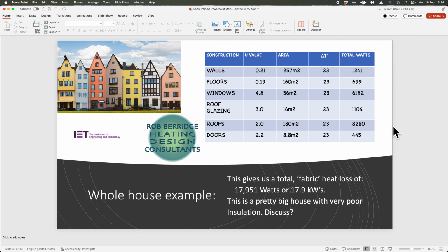But look at the windows. The windows weren't changed from day one when that house was bought, so they were single pane sash windows on there. And that 4.8 is arguably too low. That should probably be higher. That should probably be around 5.6 or even 6 as to what you would be losing in terms of U value. But again, that can be calculated. We've shown how to calculate a U value now. But there's some low-hanging fruit.